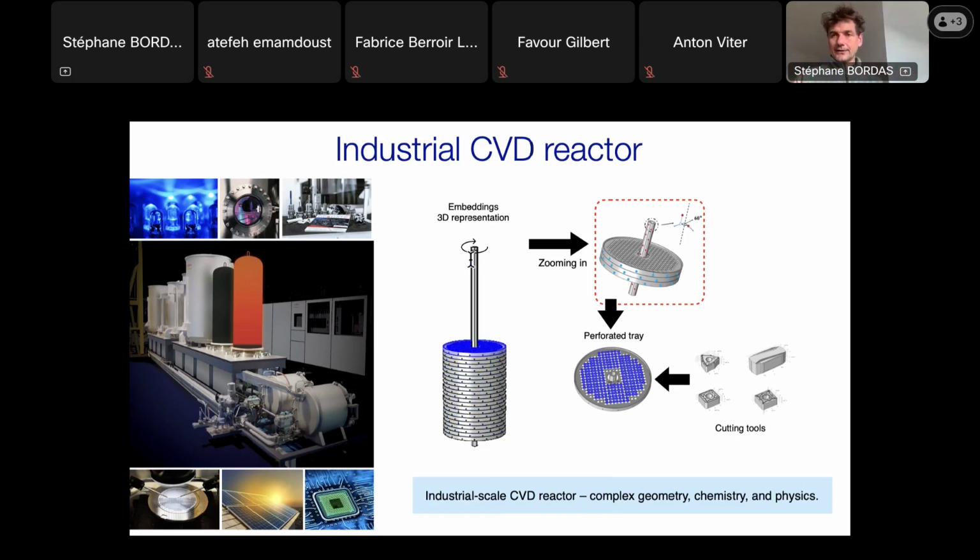And well, okay, that's great. The thing is, of course, we're making huge assumptions. So you can imagine that there is a flow in there, which you can wonder whether it's a turbulent flow or a laminar flow, and in order to figure that out, you can compute Reynolds number, which is one of the non-dimensional numbers we talked about in the beginning as well.